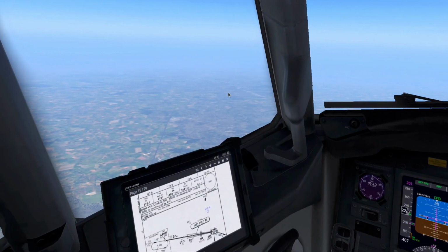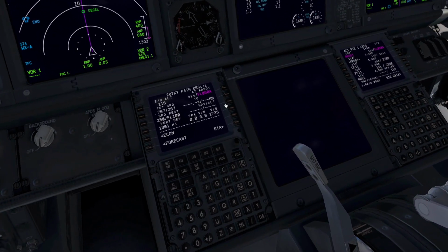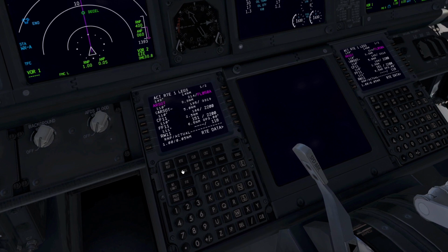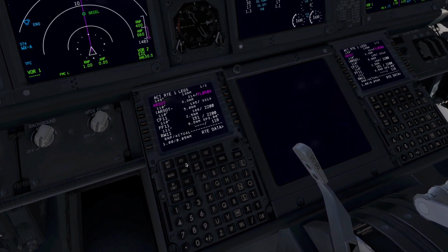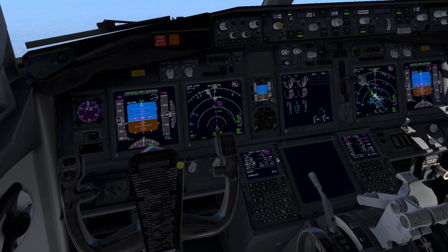However, as we get closer to the airport, the situation gets worse because we don't have much time to recover, right? So if you are too high, you can request delayed vectors for the runway, or you can just ask for a hold until you bleed off speed and altitude.